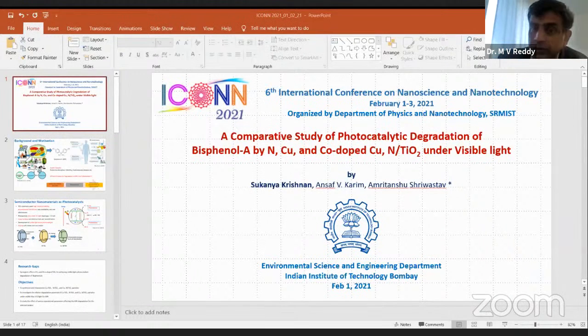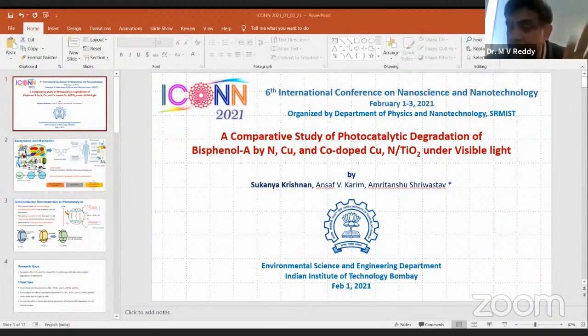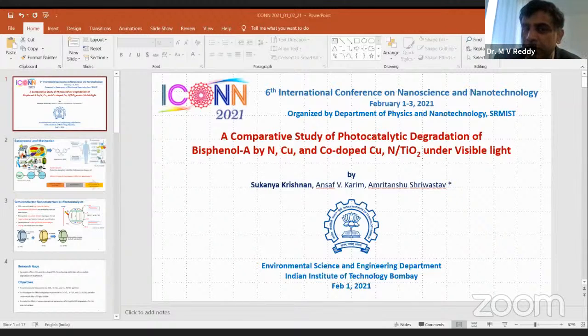Okay. Let me tell you a story. In fact, I worked a lot on doping of this TiO2, and I finished in 2012. If you remember, there is an RSC Advances paper, you can go to Google. The main problem here, my suggestion is the doping. I think we can go up to some 5%, because, for example, copper is 2+. In ionic radius, it will not match. It will, but you precipitate as copper oxide, that is normal.